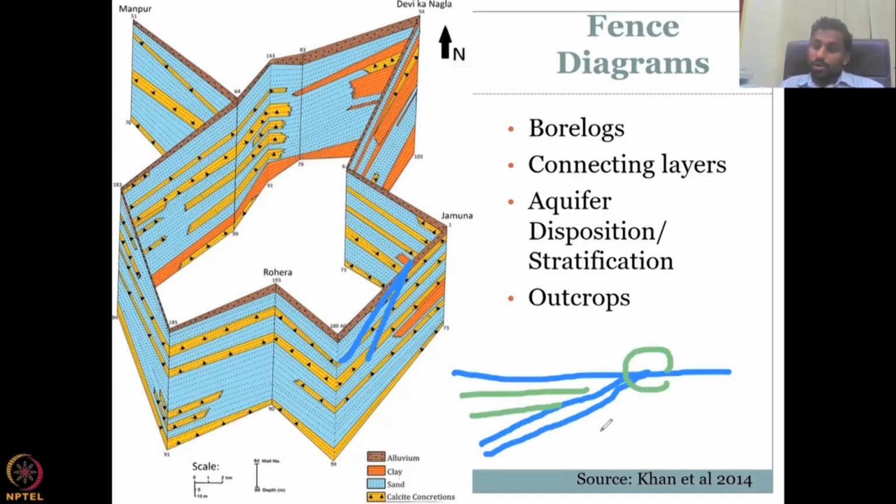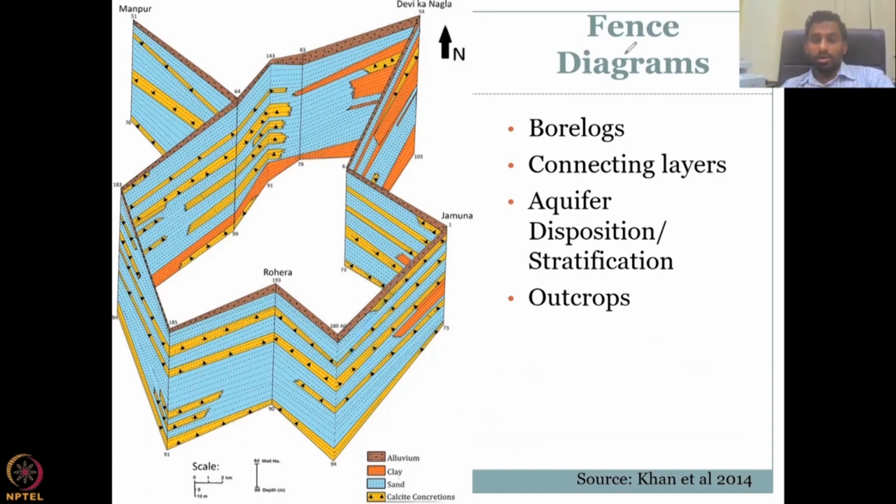An outcrop would actually divide the land underground into a couple of layers or stop a particular layer. For example, this layer stops and then another layer is here, the dominant layer is here. It's kind of a division, and that gives you an idea of what kind of water is present, and why the water is different on one side of the outcrop.